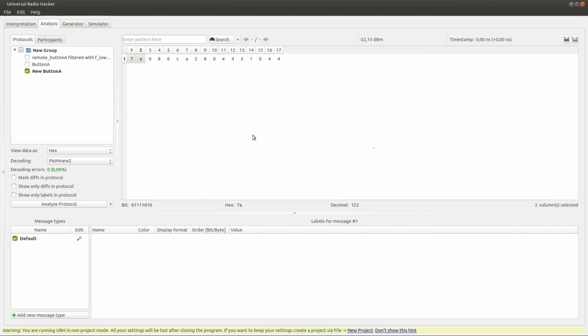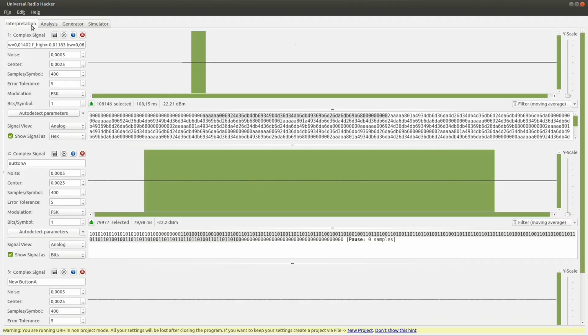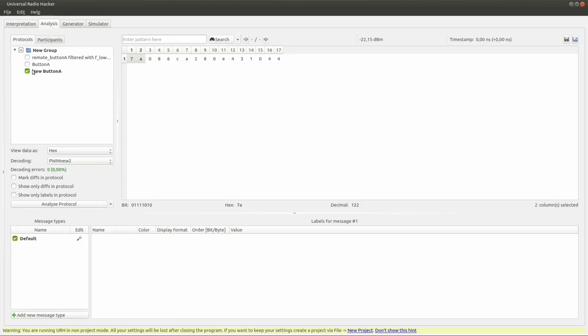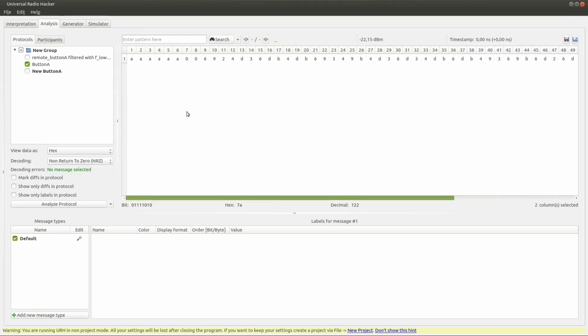So I can probably also see what is after the preamble and after some sort of synchronization bytes, but it's probably something else. Maybe it's part of these bytes, but for the moment we should probably inspect the raw bits in here. We can always try to use the raw NRZ, because the raw NRZ can be directly used, you don't need to encode it to send it over the air. You can directly send it over the air.